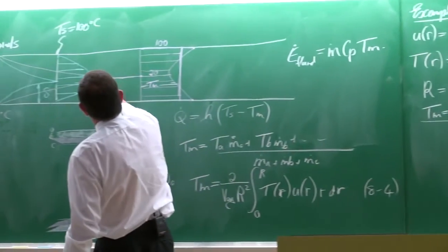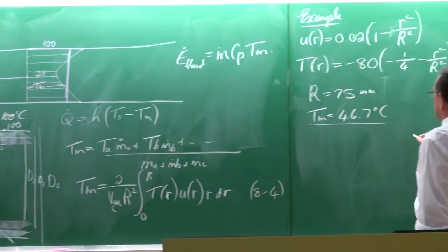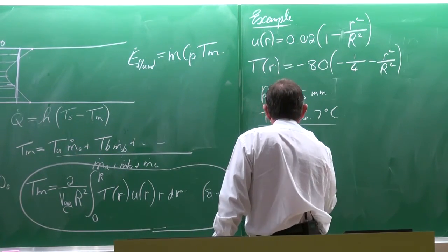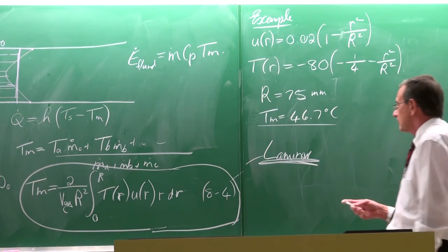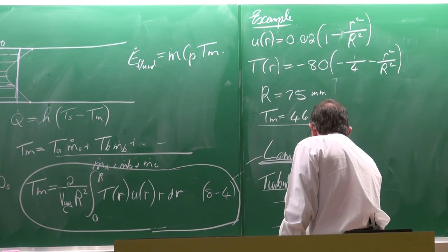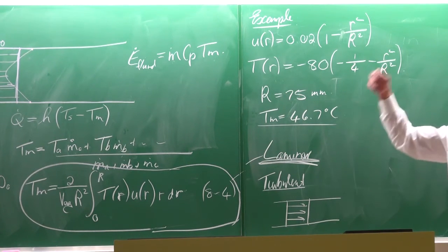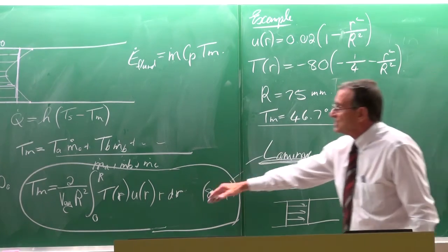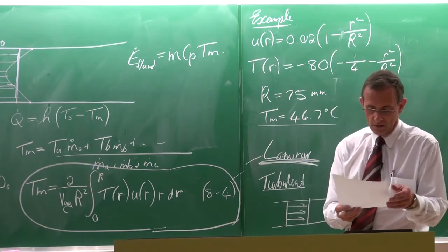Right, now you've done it with forced convection. That distance is, of course, the thermal boundary layer. Now, this is very important for laminar flow. In turbulent flow, it is not necessary to do it. Why? Because in turbulent flow, the velocity profile looks like that. It's plug flow. And because it's plug flow, the temperature profile will also be a plug flow type of temperature profile. So we only need to do these calculations for heat transfer cases in internal forced convection if the flow is laminar. It's not necessary for turbulent.